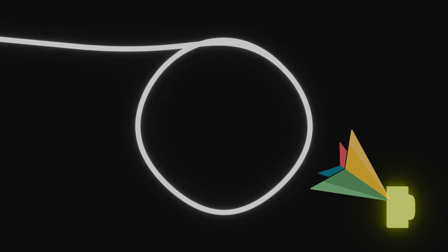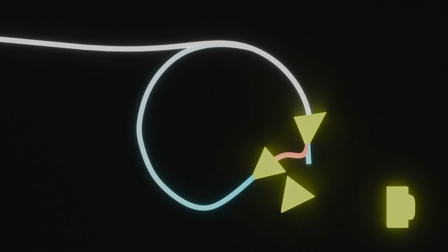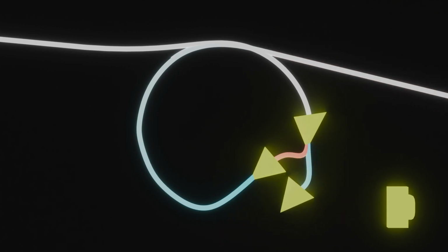Well, first let's talk output. As I mentioned, our microcontroller can send a binary output. So, for example, we have our microcontroller with the pins. Now we select a certain kind of pin and set up a loop. This loop would restart and run forever with a single if. This if on the inside will turn the pin on if it's off. If it's on, it will turn it off. Simple as it could be.